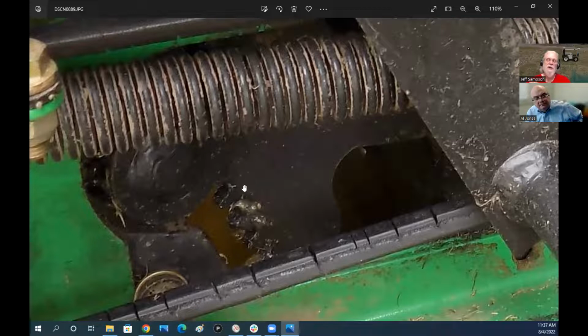Now in reality, once I get the motor under control, so if I put a feedback pot on the motor, the motor's not banging against the gear. If I start turning the motor at a constant speed, it will take up that slack and work okay. But right now, it doesn't know that the gears are there. So as soon as I hit the push button, it starts putting out, say, 30% PWM, whatever the pot is set at. And if it's going from one direction to the other, it bangs back and forth as this thing turns to take up the slop on the steering. So I don't know if I'll ever do anything about that, other than hopefully when I get the motor under control, it's not going to do that anymore.